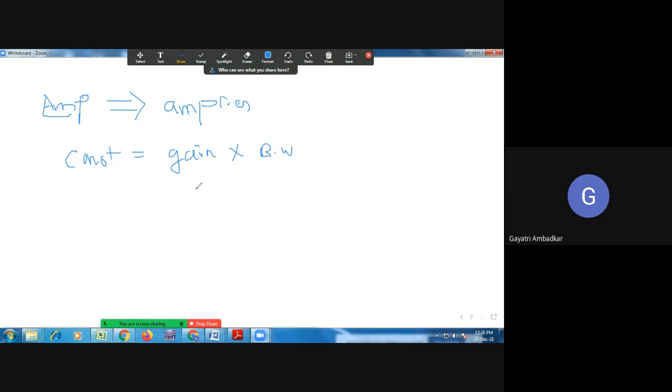So in case of negative feedback amplifier, as this gain decreases, bandwidth has to increase. It means negative feedback amplifier amplifies more range of frequency. This is the advantage, because gain bandwidth product is constant. So if you consider a positive feedback amplifier, gain will increase, so bandwidth will decrease there. Okay. So what is the advantage of negative feedback amplifier? Because gain decreases, bandwidth increases.